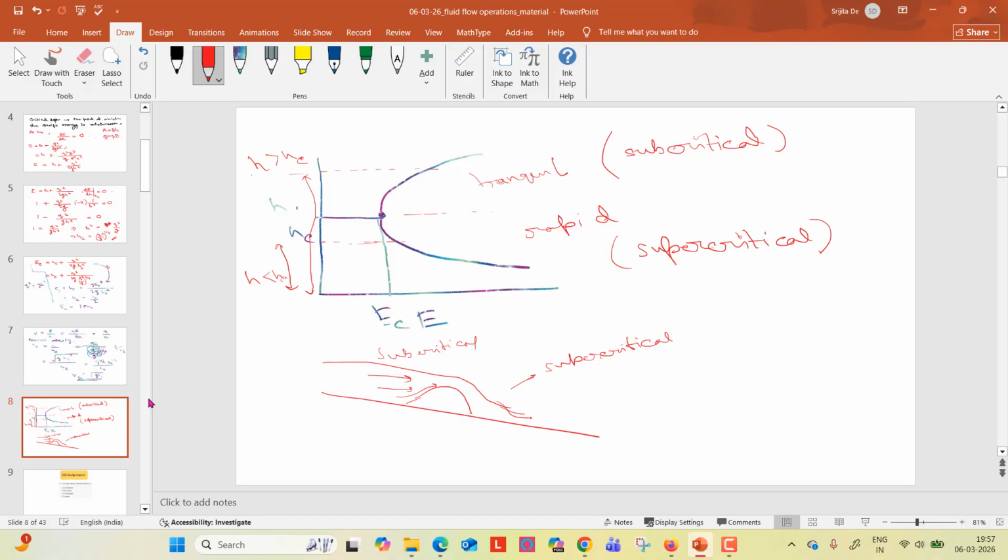And when it is jumping, the depth becomes less than the critical depth, so it starts as a chaotic mixing, chaotic motion. You can see chaotic motion, and suddenly it will create a backflow kind of thing. After some time it will experience a backflow, and it wants to go back to the subcritical zone, and it creates a hydraulic jump here. So this is your hydraulic jump here.